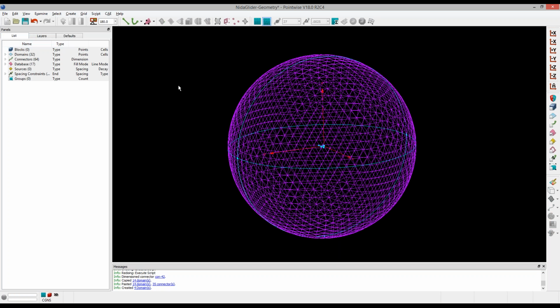And if you have quads, to transition to the triangular faces of the isotropic tets is going to require a pyramid. And so I'd have a layer of pyramids over all of those quads out there in the far field. There's no reason for that. Just leave it as tri to match up perfectly with the isotropic tets that are out there. Okay, so that's why I've gone ahead and done that.